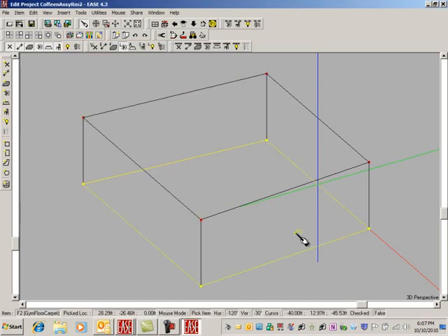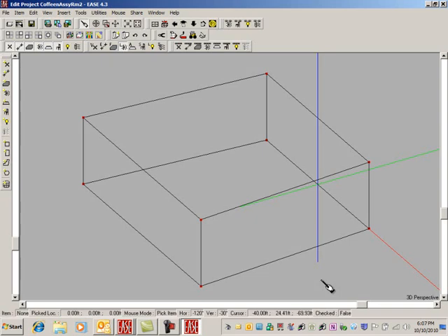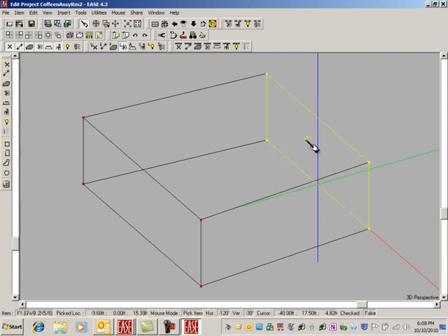And when I do, I get this little, you see that X there? Well, I know that it wants to be at about minus 22, and I'm going to move my cursor way down here. This stuff shows where the cursor is. And I'd like it to be minus 22 about, but I can always edit it, so I'll just put it somewhere there. And it's not quite right. If I wanted to see what it was, I could select it here and do an F4. F4 is always properties, and it says it is at minus 22.33. Well, why don't I just fix that? I'll make it minus 22. Say okay, now it's in the right place.